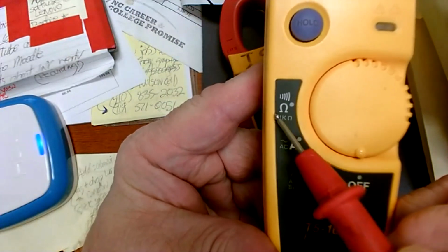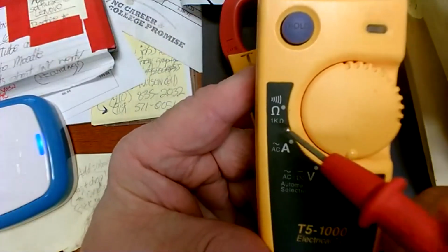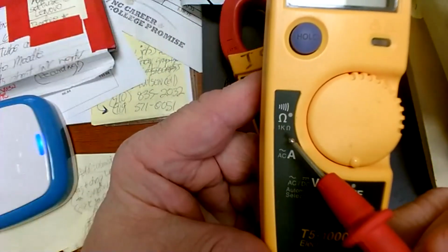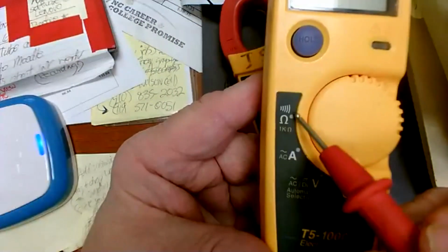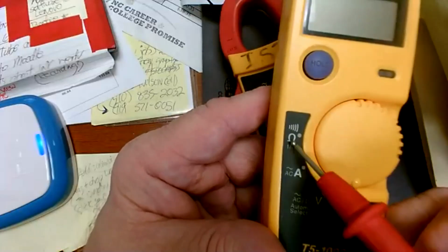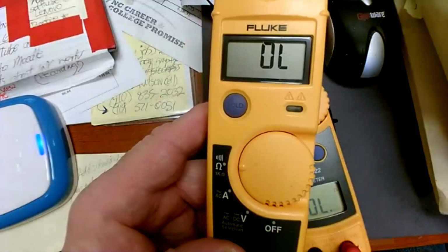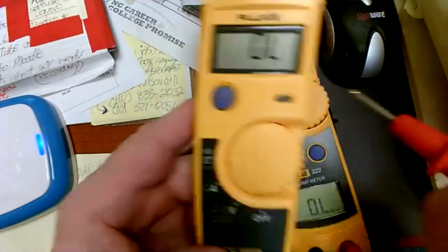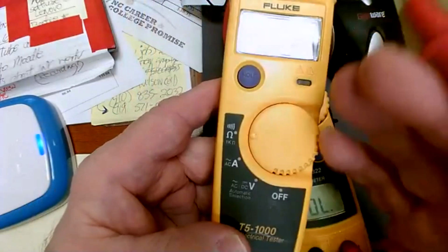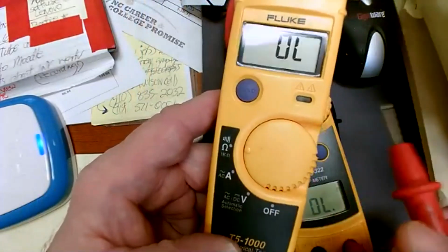1 kilo ohm. 1 kilo ohm, and the K means what? 1,000. So the limit of this meter is it won't read any higher than 1,000 ohms. Okay. If you go very far above 1,000 ohms, it may go a little bit above it, but it isn't going to go far. If you get around 1,500 ohms, 2,000 and up, it's going to say OL. Okay, so it has that limitation. This one is very limited on resistance range. It won't go high in kilo ohms and it won't read any mega ohms. So this is just for a very limited amount of things you can do with it.